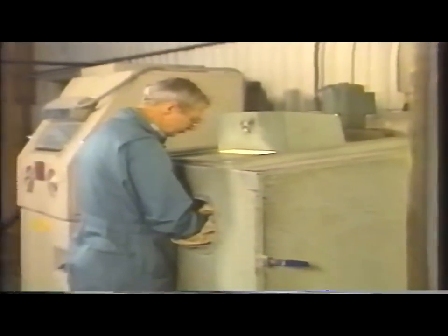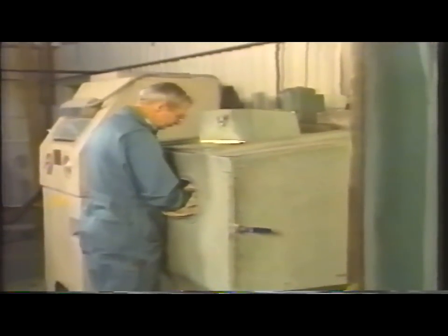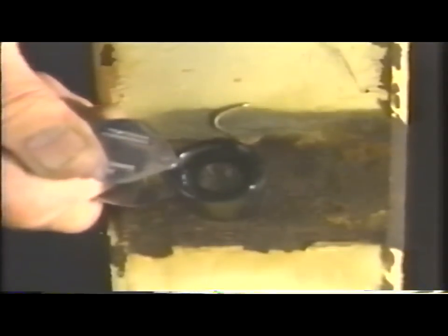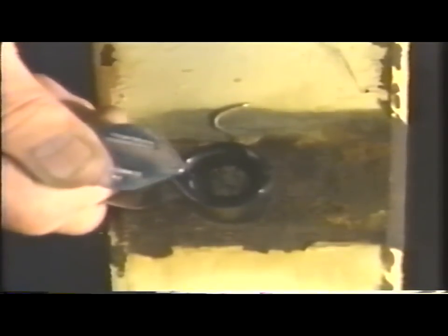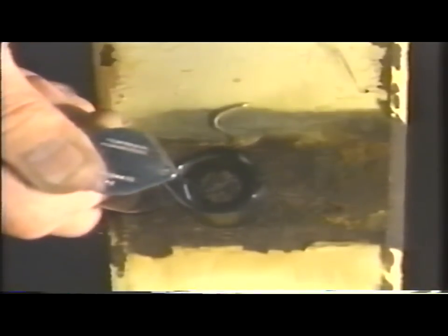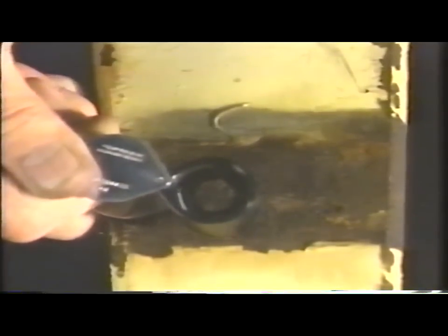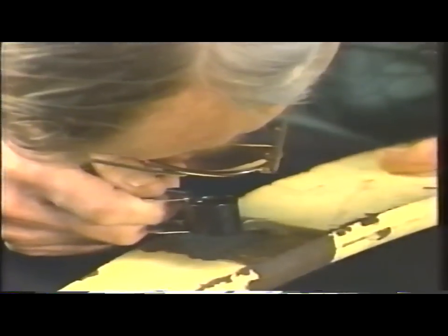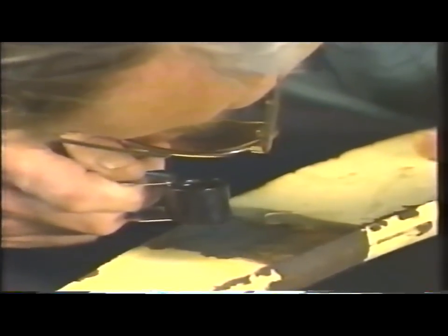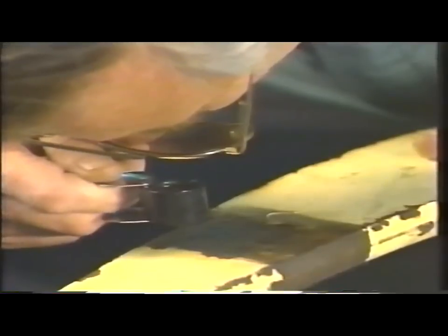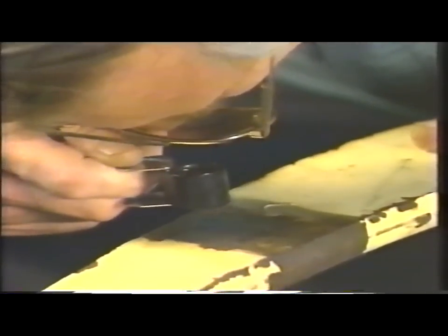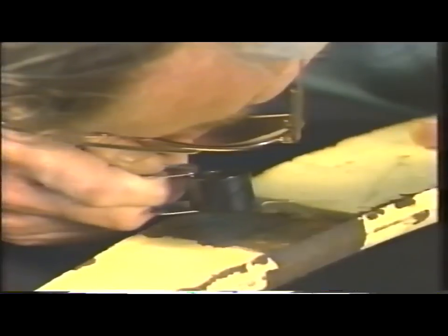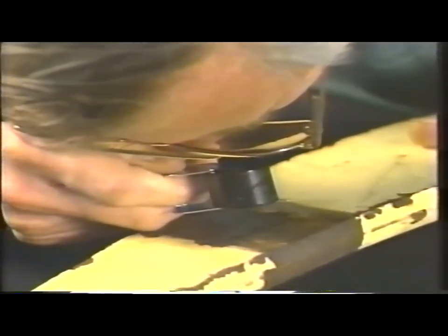Abrasive blasting is the most thorough method for removing rust from both low alloy steel and high-stress steel surfaces on the aircraft exterior. It's important to remember that the smallest amount of rusting on a highly stressed steel part is potentially dangerous. The rust should be removed and controlled to prevent possible catastrophic failure of the part. Additionally, any surface abrasions or changes in surface structure from overheating can cause sudden failure of these parts. It is essential then that steel surfaces not be overheated during corrosion removal.